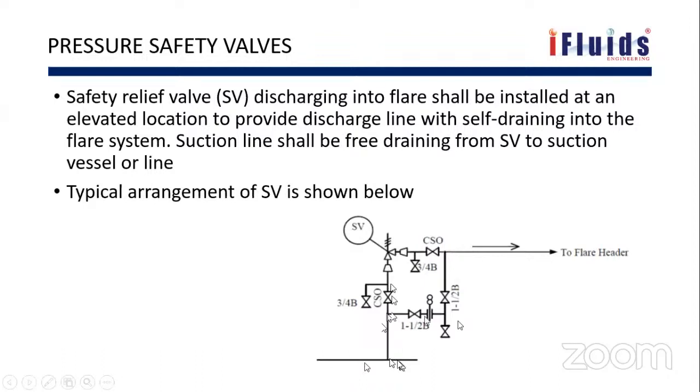And the PSV is also provided with a bypass. These are purely for decontamination purposes or during shutdown. It's used only for shutdown and maintenance. In normal operation, this bypass line of any equipment, especially a PSV, is always kept closed and blinded. Because if it is not blinded and if these valves are passing or have failed, we'll have the fluid going to the flare header. This is a loss for us. So this is to be kept blinded.